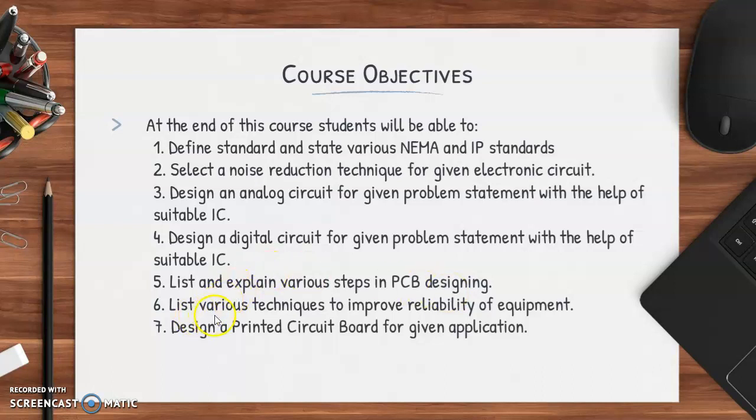Students should be able to list various techniques to improve reliability of the equipment. Students should also be able to design a printed circuit board for a given application. Designing a printed circuit board means we will have to go through all the major steps like finalizing the circuit, its layout, its artwork, drilling, etching, soldering, everything, isn't it?